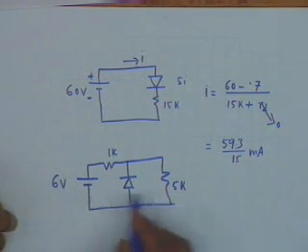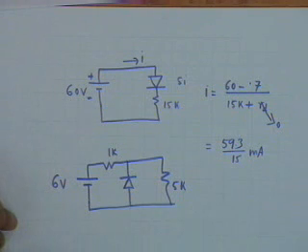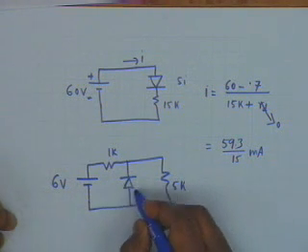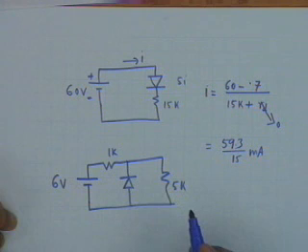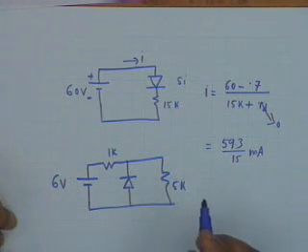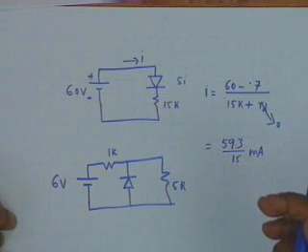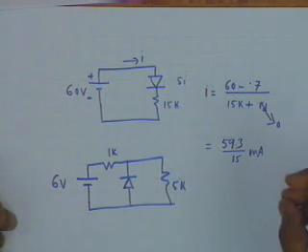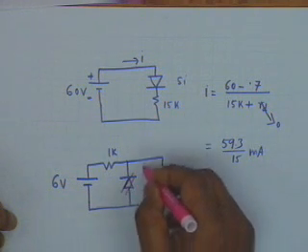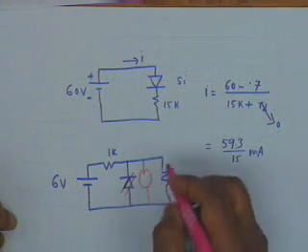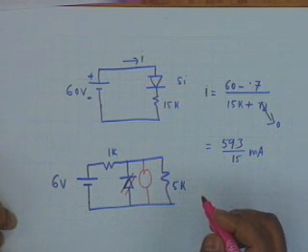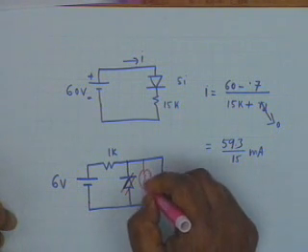If I have a diode like this, then obviously this diode is reverse biased, and in reverse bias you can ignore the ideal diode, the threshold voltage, and the dynamic resistance. So all that you have to do is to replace this by means of IS. Now will it go down or up? It will go down.